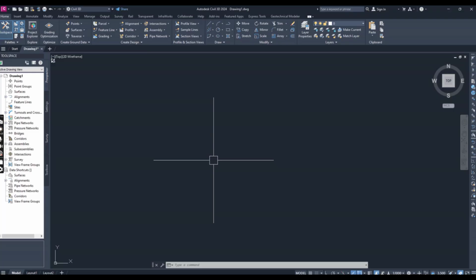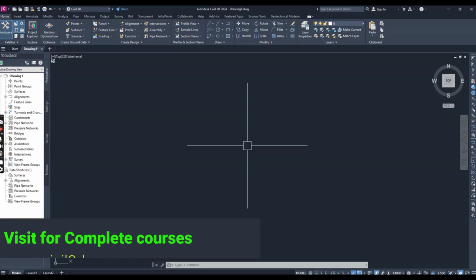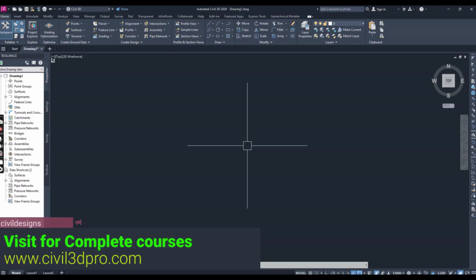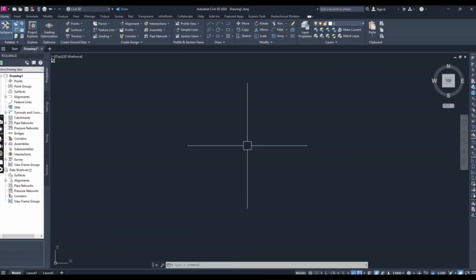Profile views will be an integral part of Corridors, as we will discuss in the next chapter. In this chapter, we will look at using profile creation tools, editing profiles, and generating and editing profile views. We will also apply labels like we did in the previous chapter for alignments. So our goal in this chapter is to sample a surface profile with offset samples, lay out a design profile on the basis of table data, add and modify individual entities in our design profile, and apply a standard band set.